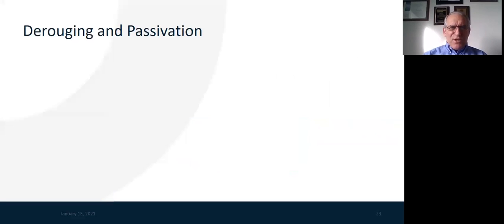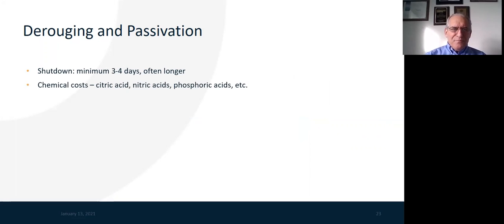So what are some applications? Well, the idea here is when to perform derouging passivation. Derouging passivation often is a minimum of a 3 to 4 day downtime and longer for its application, depending upon how large your water systems are, how many loops are in your water systems, and whether you're passivating both your purified water system and your WFI water systems as an example.